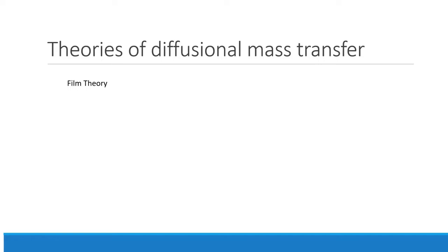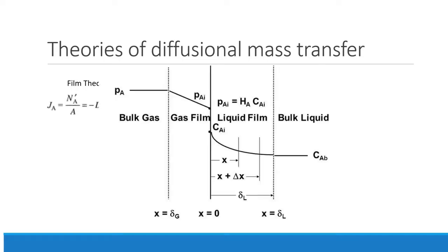It proposes the concept that a stagnant film of constant thickness, denoted as del, exists between the phases at the interface boundary. Generally, there will not exist any concentration gradient within the phase, since it can be equilibrated by agitation. But however vigorous the agitation may be, the diffusional film exists, which in fact offers resistance for the mass transfer to take place. In this film, the mass transfer takes place solely by diffusion.